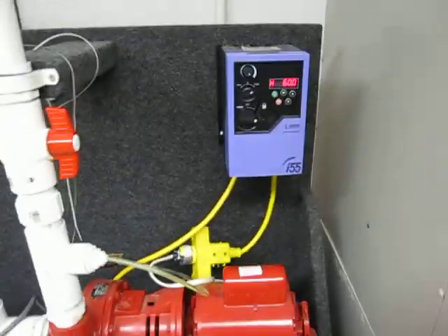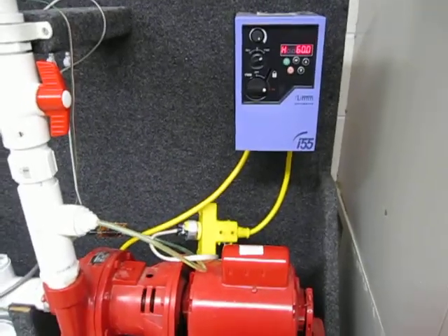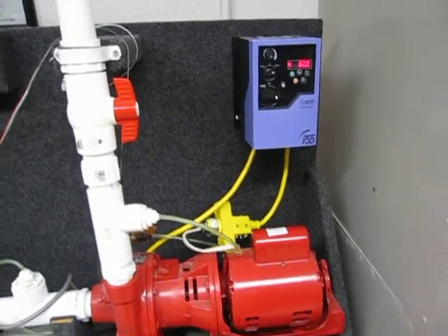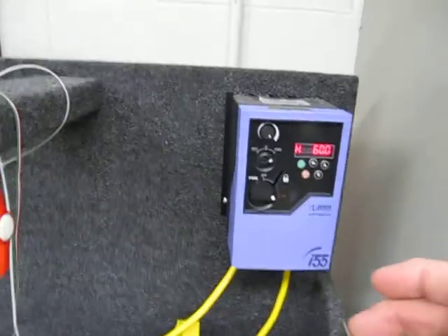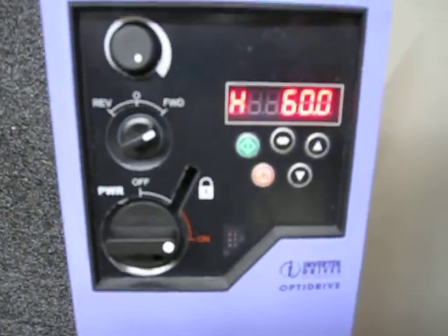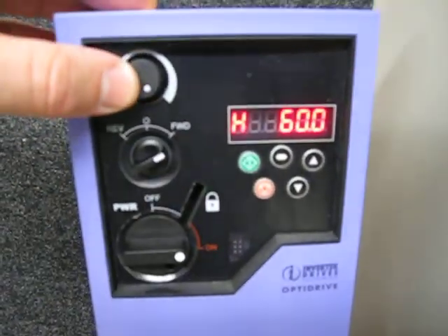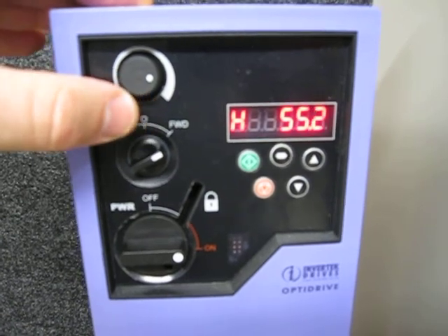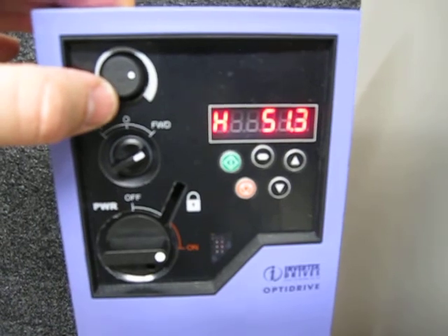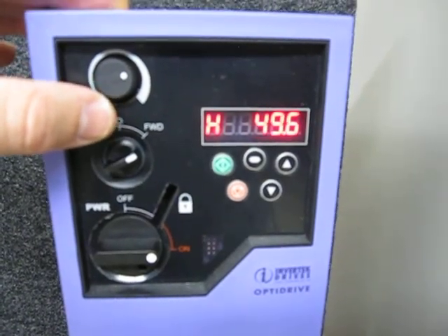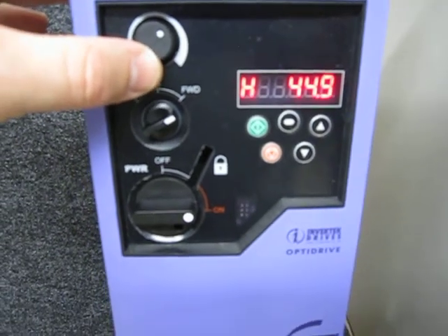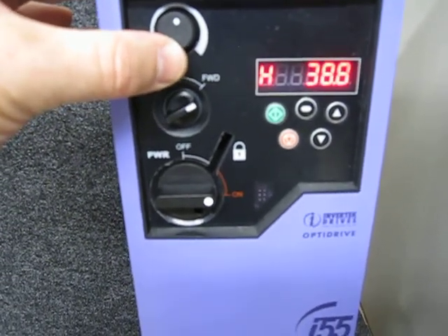Now we're running through the variable frequency drive. It sounds about the same. We're going to do something different though. We're going to find that we can control the speed by controlling the frequency. And if we look close, we see we've got 60 Hertz showing. I can adjust this knob. I can bring this down to slower and slower frequencies. It changes from 60 Hertz at the outlet to right now about 49 Hertz, and I can keep slowing it down. You might be able to hear the pump slow down in the background.